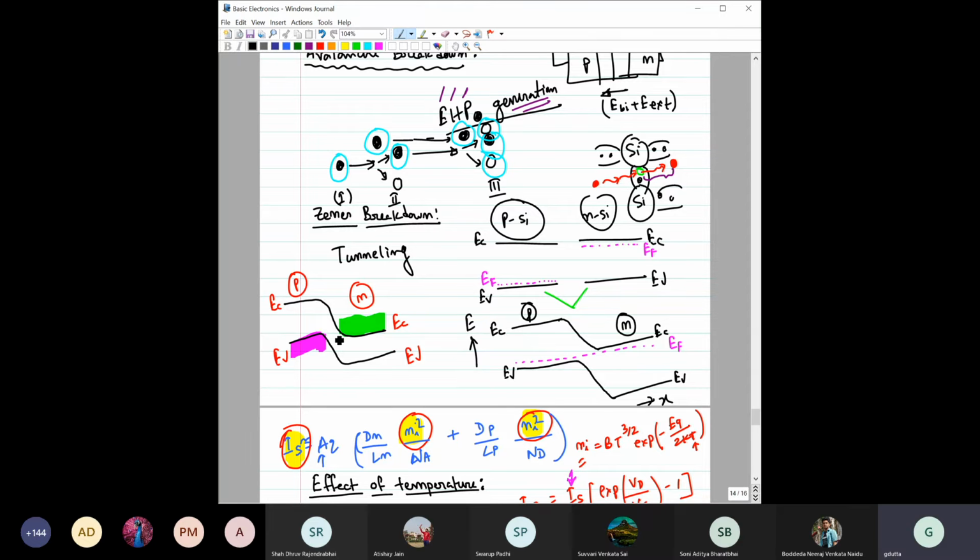Now you can see, if you reduce the gap between these two so that it becomes very small, then you are basically separating this huge amount of electrons from a region where the electrons are not that large in number. As a result, these electrons from the valence band will directly go from here to here. You can think of this as a tunneling process.